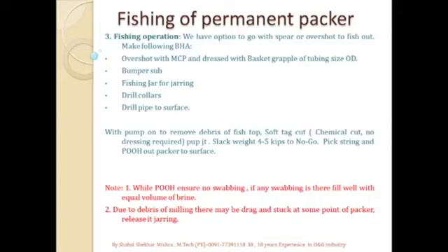While pulling out, ensure no swabbing should be there. If any swabbing is there, we will fill the well with an equal volume of brine to maintain the hydrostatic. And due to debris of milling, there is a chance that the packer may have drag or get stuck at some point while pulling out.